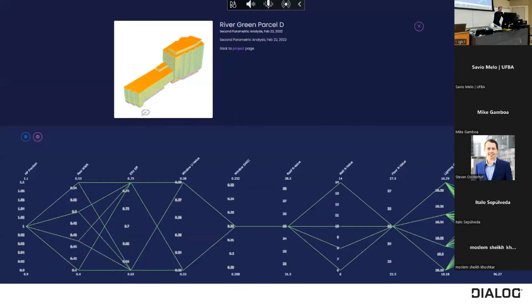We use this a lot with sustainability. So this is a parallel axis plot. So for almost every building we do energy modeling. And energy modeling is influenced by things like your window to wall ratio, how many windows you have, the R value of your walls, the total energy load, the efficiency, and all together that gives you what's on the right as the output, which is your energy use intensity. But there are many different paths to get to your target.